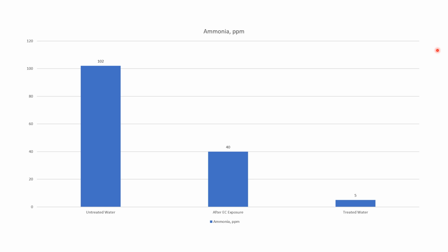The zeolite media spent quickly, and we found ourselves having to change out the media on a weekly basis. Removing and recharging 5 metric tons of zeolite once per week turned out to be quite a logistical challenge. It also introduced another waste stream of spent media, which was not desirable.